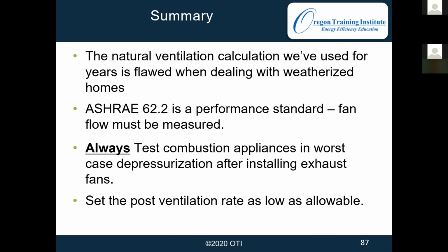So in this section, we covered a lot of information, from what the different contaminants are in the house, how to reduce them or eliminate them, or if we can't, just dilute them down with our fans. We covered what kind of fans are required, like spot fans in the bathrooms and kitchens, and then usually a whole house fan, which can be located in the bathroom or kitchen.